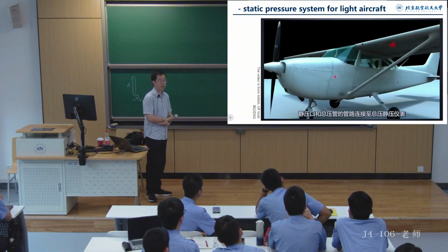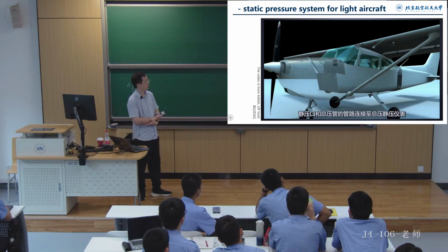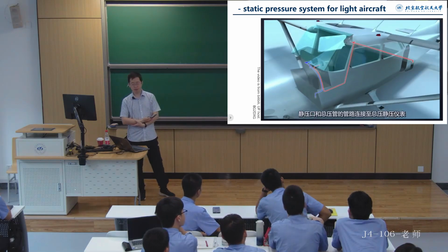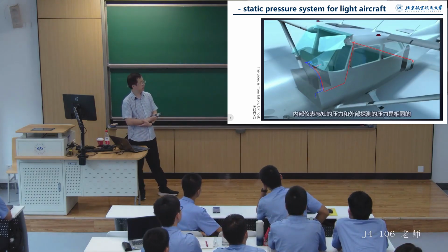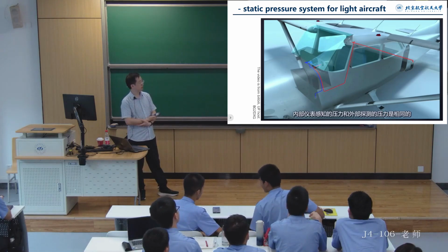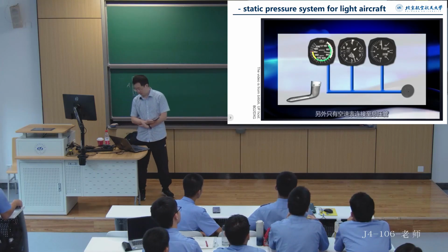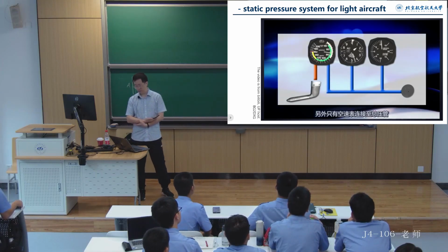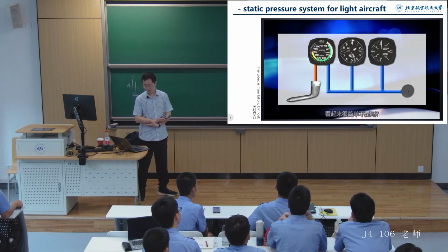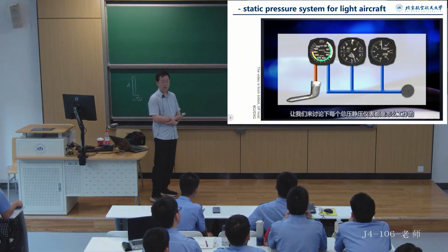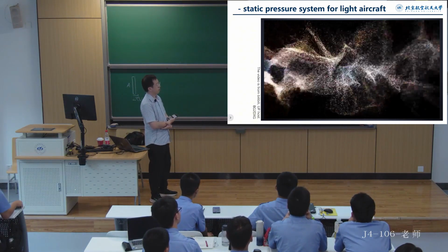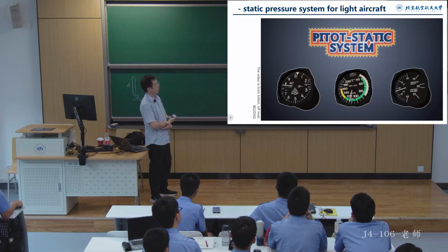On the Cessna 172, the static port is located on the left side of the forward fuselage. The pitot tube and static port openings are connected to tubes that join into the pitot-static instruments. The pressure inside the instruments matches the pressure of the outside atmosphere. All three pitot-static instruments connect to the static ports, but only the airspeed indicator connects to the pitot tube. Sounds simple, right?